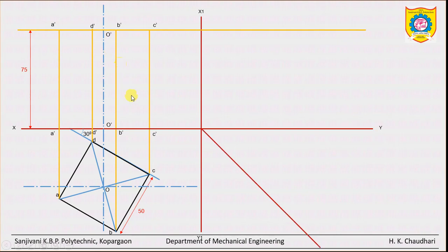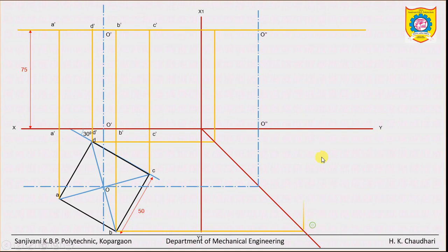Clear? Now to obtain the side view of this prism, just draw this 45 degree inclined line and extend the axis first. Now just draw the projections from each corner here. Now these projections become the edges in the side view, in this way.